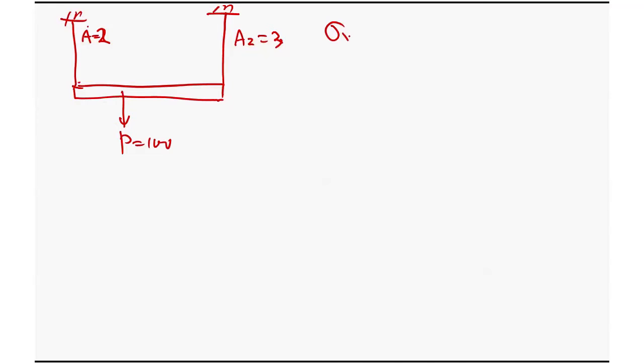So we know the sigma y. I will use the same value, 200 megapascal. Okay. All right. And I want to check. So basically, for ideal design, all right, we want a safety factor of say 2, right, or 4, right? You give a number. Let's say we want a safety factor of 4. We use the same. Okay.